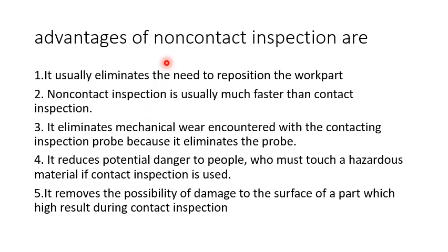So we need to understand the advantages of non-contact inspection methods. It usually eliminates the need to reposition the part, which we have already discussed. Again, non-contact inspection is usually much faster than contact inspection, and it eliminates mechanical wear encountered with the contacting inspection probe because it eliminates the probe. Fourth advantage is it reduces potential danger to people who must touch a hazardous material if contact inspection is used. Fifth advantage is it removes the possibility of damage to the surface of a part,